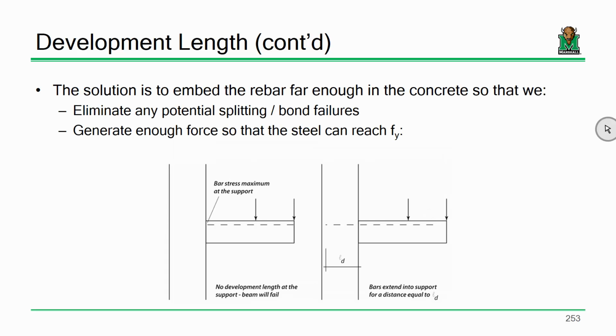Again, here's my concrete beam. This is the cantilever. The top of the beam is in tension, so we put the bars on the top of the beam, as opposed to the bottom. Going back to my original example, party deck, dance floor, rebar on the bottom, no time to whip, let alone nay-nay.